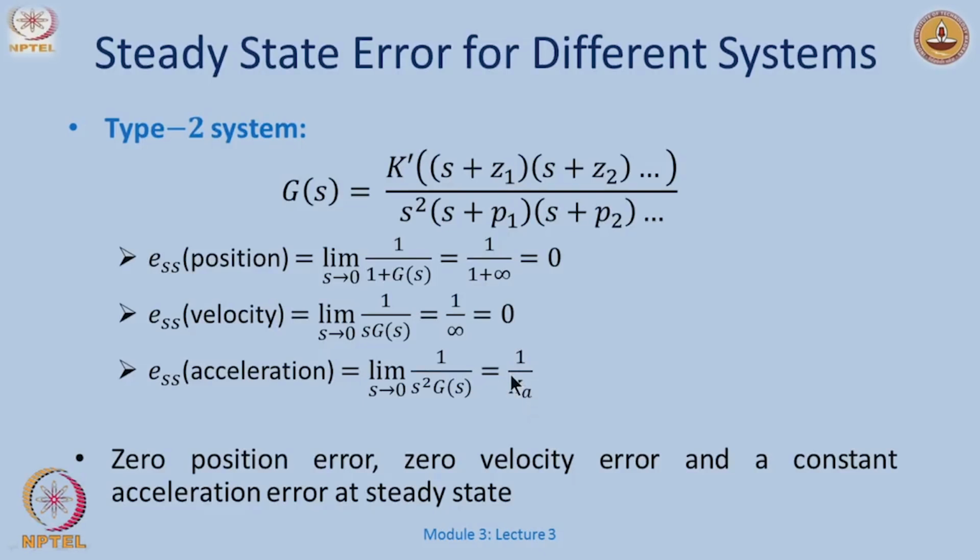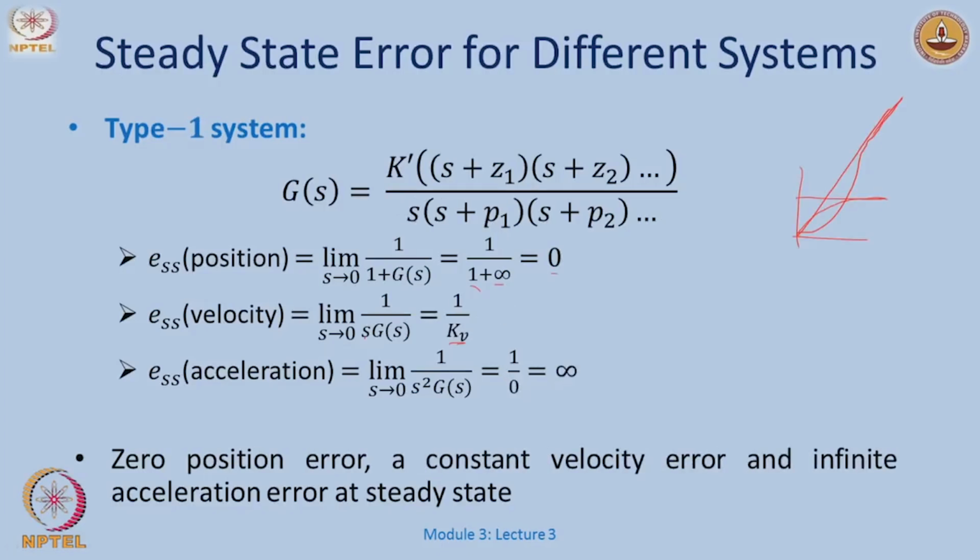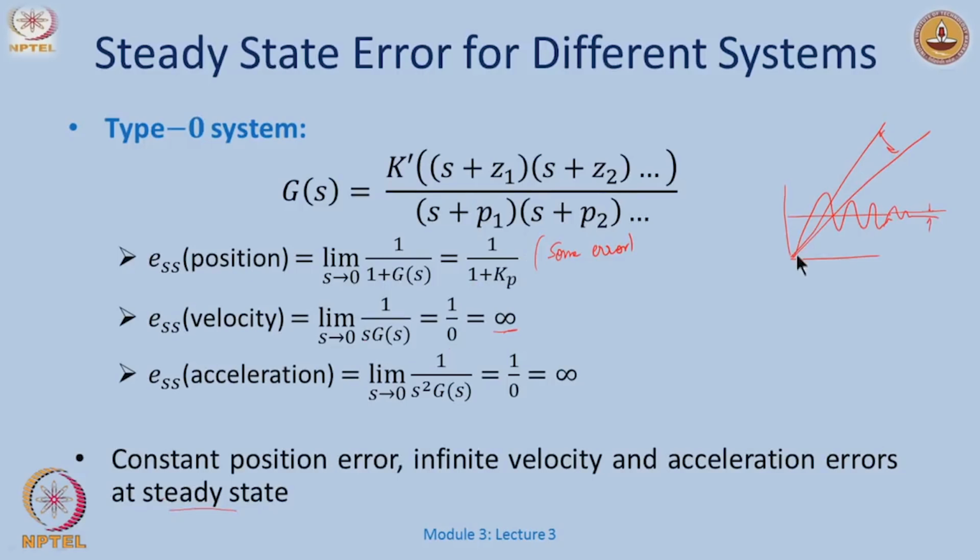Okay. Now, we see that if I give a little problem saying take a type 0 system and make the position error 0, what would I do? I will just say, okay, remember all this theory now, and I say just put an integrator, right, or add a pole at the origin. This is a system which has more poles than zeros, I can possibly always realize this, and I can just put it here, right. So, can this be done, can this not be done, or can this be done with being a little careful, we will see all those things.